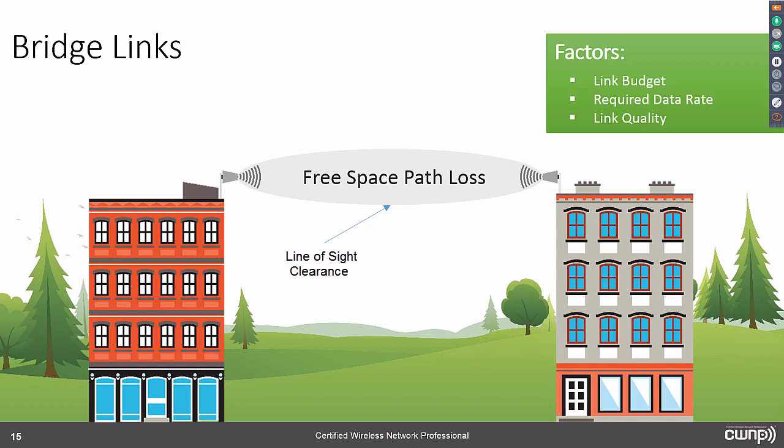So most regulatory agencies, they're going to limit your output power at the intentional radiator and your equivalent isotropically radiated output power in some way. And so it's important to understand those regulations wherever you are in the world. But generally speaking, with an understanding of those regulations and then the choice of the right antenna, you can create links that can span several miles.